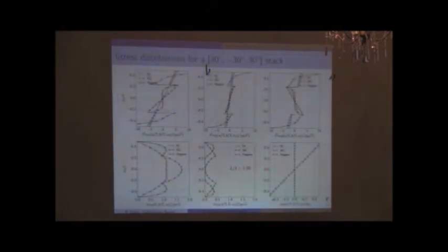So I will first show the stress localization tensor. So the three graphs at the top are the in-plane stress. So sigma 1,1, sigma 2,2, and sigma 1,2. Those sigma 1,1 and sigma 2,2 are taken at midspan of the plate. Sigma 1,2 is taken at the boundary, at the support of the plate, and those two are the transverse shear. They are taken at the boundary, on the edge. This is the position where the shear force is maximum.